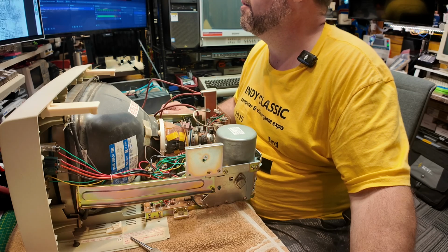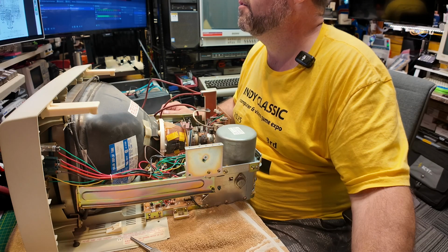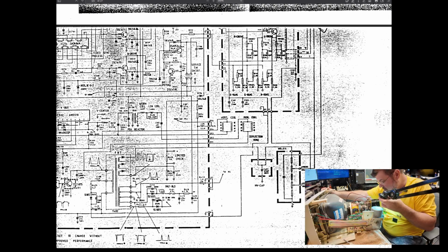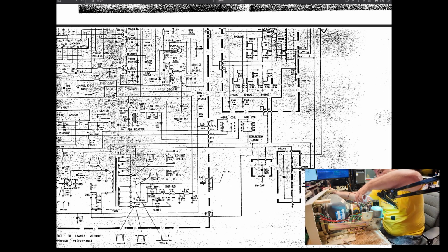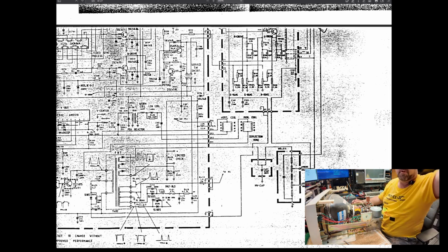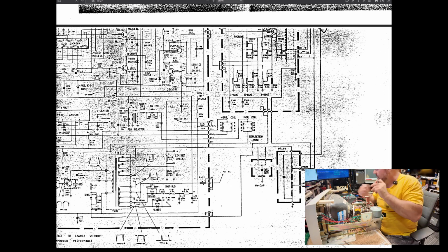On the schematic here, does it say what color the wires are? No, because that would be helpful. DY1, DY2, DY3, and DY4. Okay, it's 1, 2, 3, 4 labeled from the back of the board. So 1 and 2 are horizontal, and that is blue and red. Okay, so it's the back 2, and then the front 2, green and yellow, are vertical. Simple enough. Let's check that.